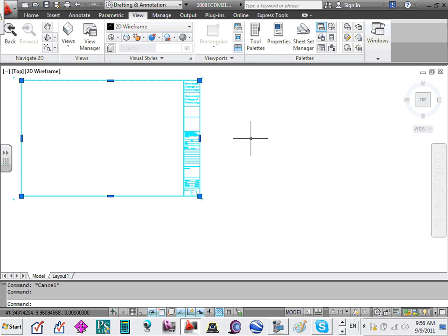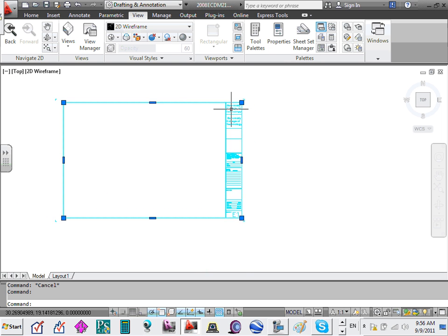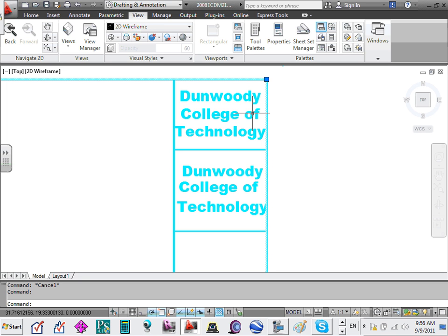What I suggest, guys, is not to mess around with this. Now, Phil, if you decided you're going to go get the title block that you guys use at work and use it here, fine with me. What you have to do is just give it the same name. Name it the same name like we did here. What was the name? 2008 ECDM, blah, blah, blah. Give it the same name. Save it in that folder with the same name. It tells you, do you really want to replace that? You say yes, and it populates your new title block.